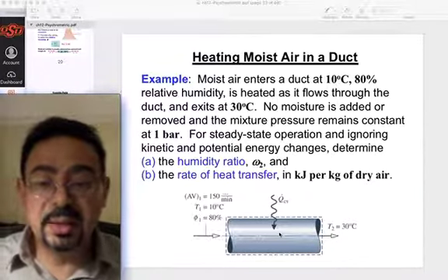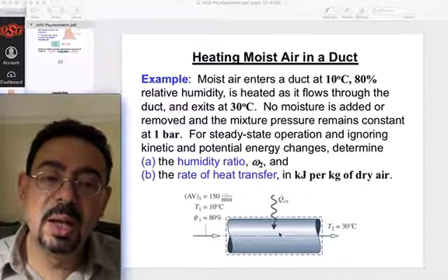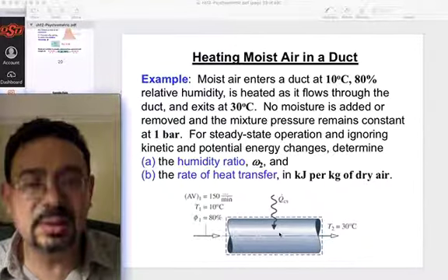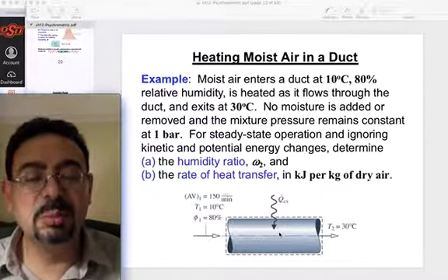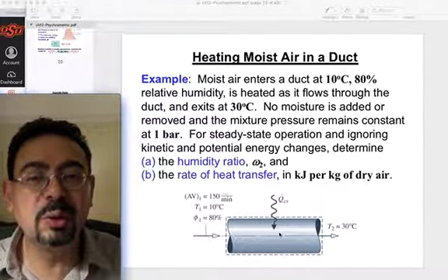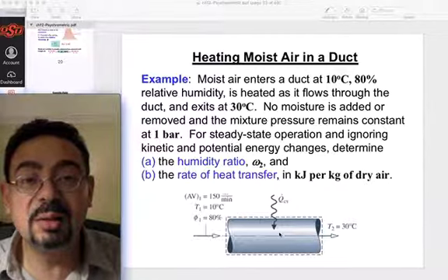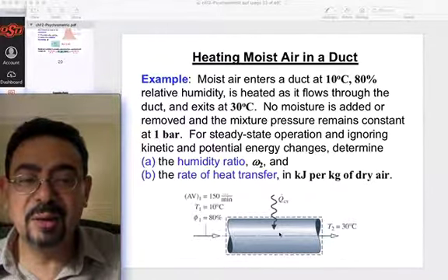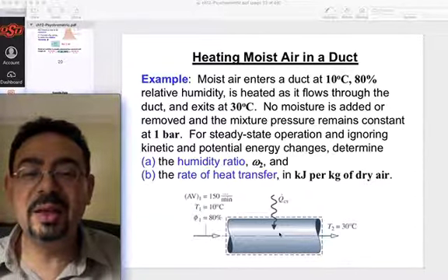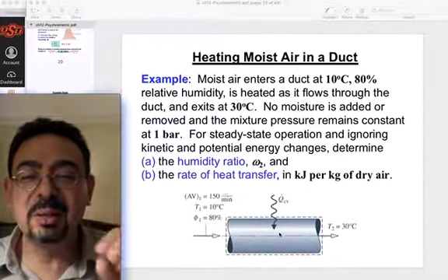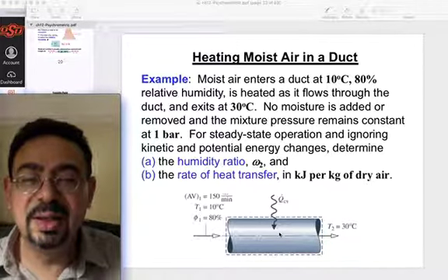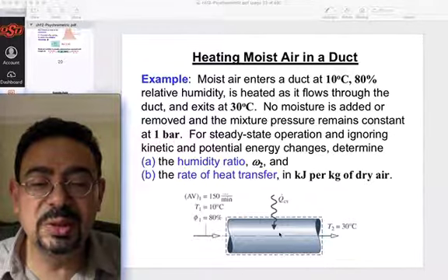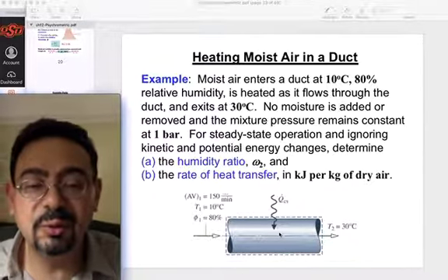And that is also the case in fluid mechanics. If you remember, in every scenario, whenever they ask you for calculating the force and you say, yes, I would use the momentum equation, most of the time you also need the continuity equation to start with. Because m dot is always there. In the momentum equation, there is m dot out V out minus m dot in V in. In the energy equation, there's also Q dot minus W dot equal to m dot h out minus h in. So the m dot is always there, and so the continuity equation is a given. You have to use it.